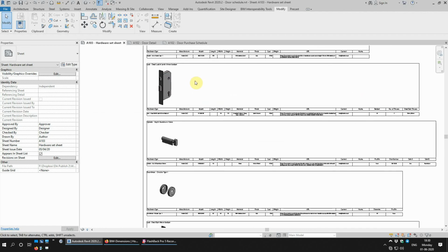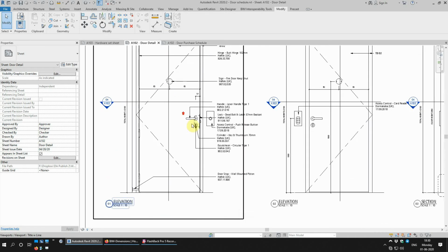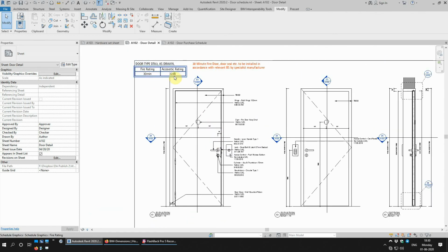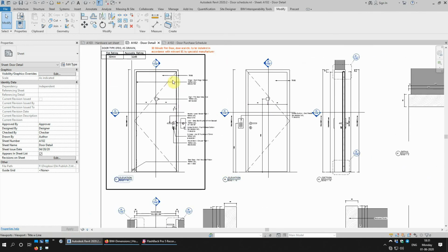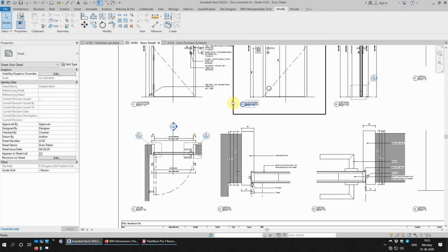Now, how does this information get used? We then prepare a door schedule. So from that hardware piece, we prepared a door schedule, and we've obviously added more information. But for instance, for that lock, you will get this kind of information here for that lock derived from the schedule. You don't have to manually enter any of this. This just gets added from the model that you've already created, or that we've already created. And we added further information like the fire rating, acoustic rating, finishes, and dimensional information like the leaf heights, total heights, clear widths, clear openings, and so on.